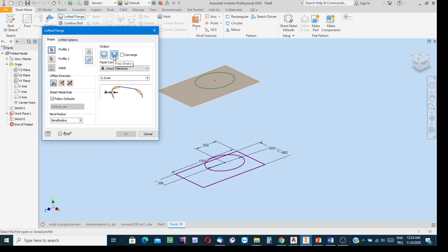In practice, we use two different technologies for creating a loft via bending the sheet metal: by using little flat surfaces, or by using a specially designed die mold with a continuous surface, have the passing from flat surface to the adjacent flat surface.